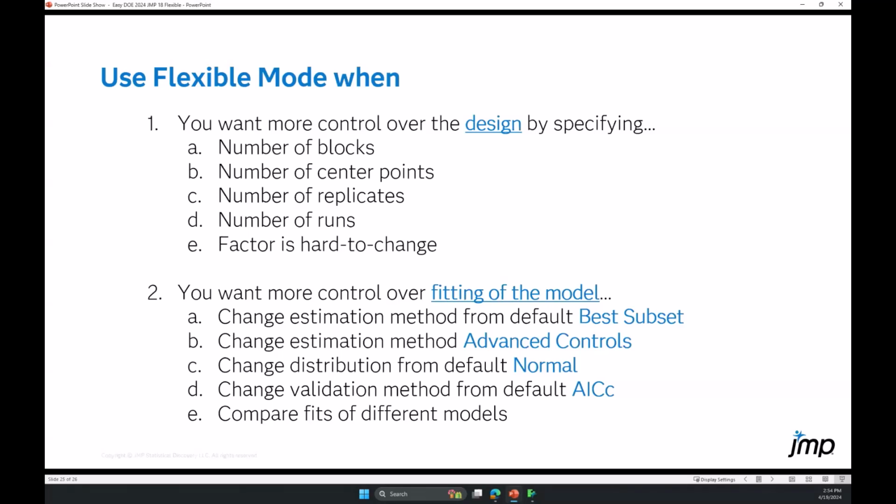And what is a block? Yeah, whole plot is associated with the way that the models are going to be analyzed. When we block, it's usually we're blocking across. I got 3 bags of raw material, and I think they're all the same, but one's got maybe an older date code. And it's more like a check to see, is that bag so much out of date that it's shifted the process, or the shift from day to day. We don't really think there should be an effect, but it might show up. Whole plot is more about the variability within that setting is larger than, say, the between factor settings. So there's like factors within a plot and factors out.